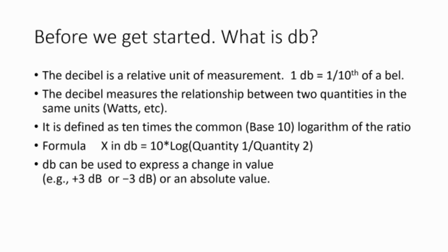dB can be used to express a change in value. We would use that sometimes in amateur radio. You could say plus 3 dB or minus 3 dB, referencing something so that we know what we're referencing. So if I'm running 50 watts and I put my power output up by 3 dB, I'm now running 100 watts. I'm doubling my power.